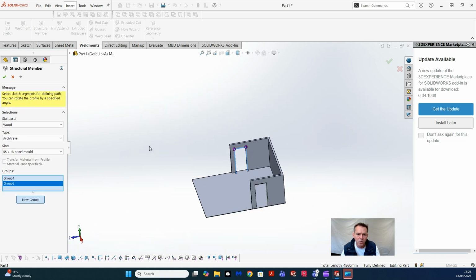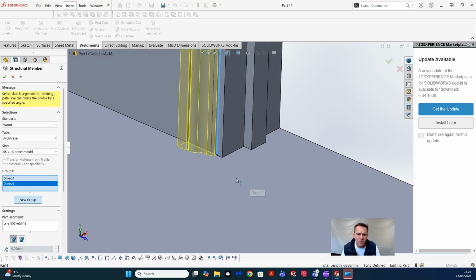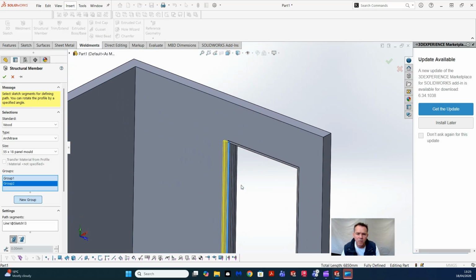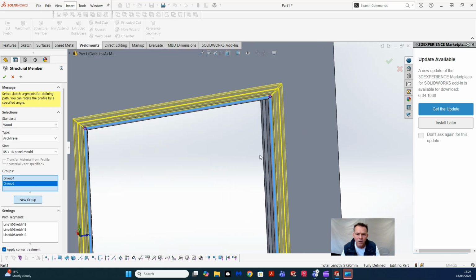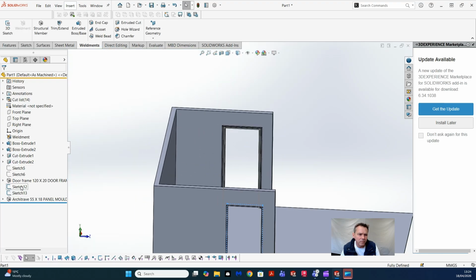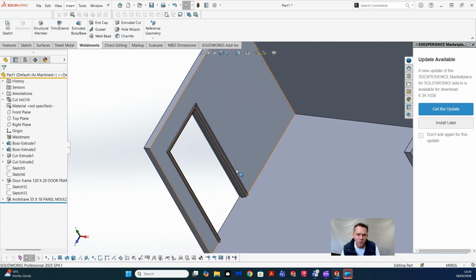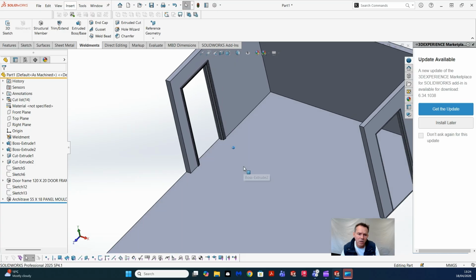We're going to start a new group. We're going to click on this one. Once again, orientation has come in spot on what we want, so that's fine. We don't have to mess around with realigning it. Tick it off. Let's hide away the sketches. And there you go. We've got 2 sets of door frames, okay, and with their architraves.